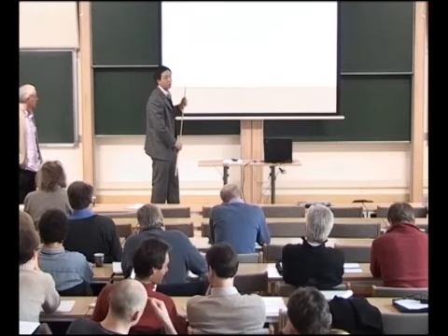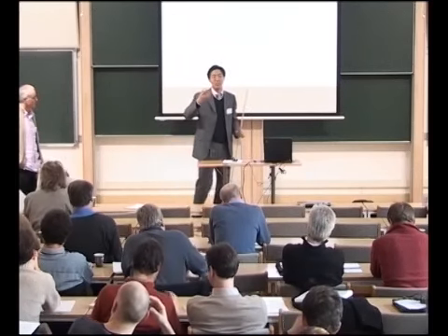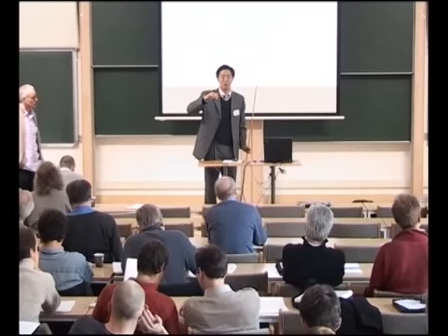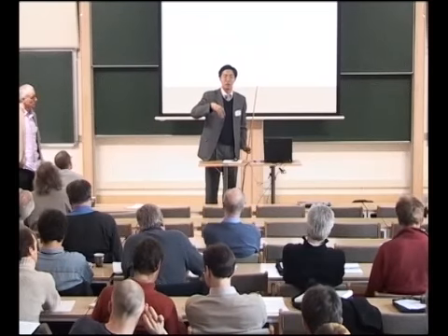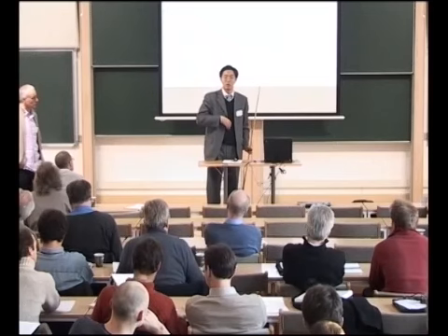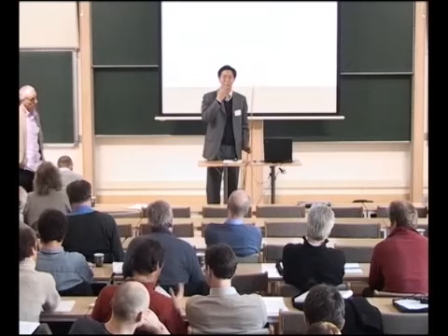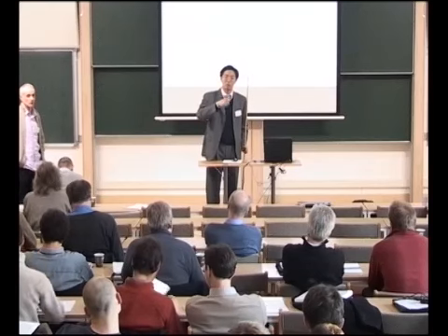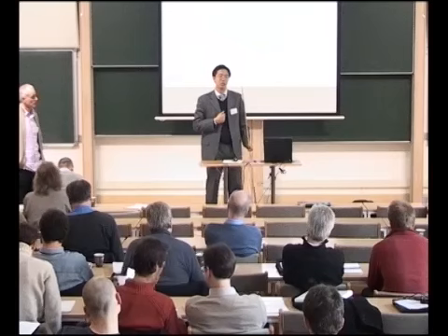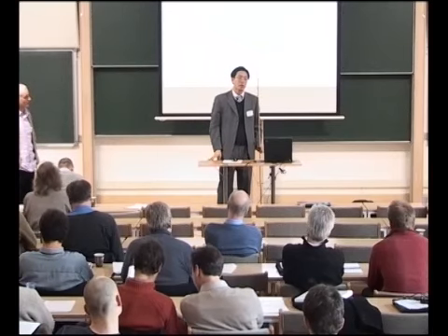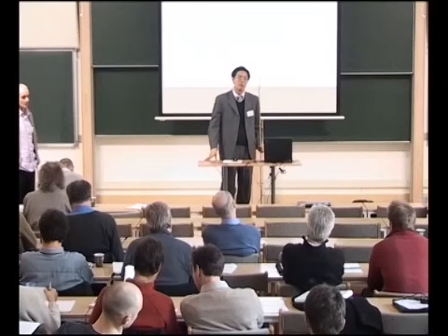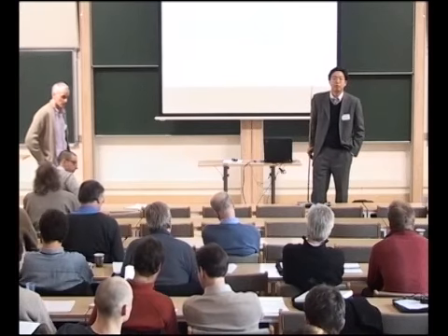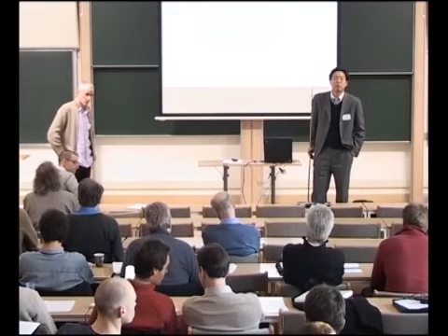We don't change the mass; only the volume fraction changes, just like this. But how to relate this zone to previously existing theory like the JKR and develop the adhesive contact is still a lot of work we will do. Currently I just find that the sliding in the adhesion is much more important, but the effect of the normal force, according to my previous work, is limited.